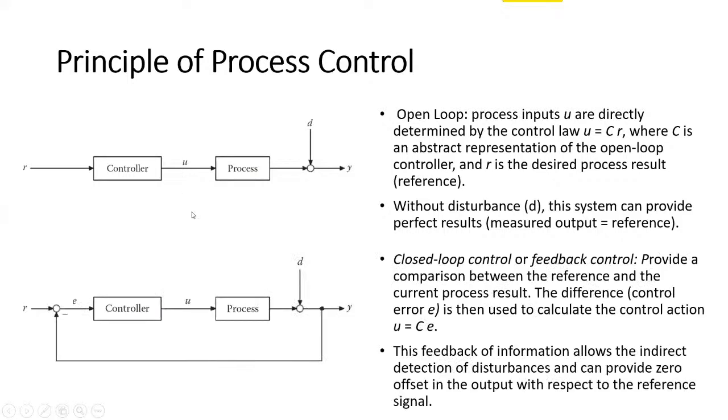So we now use a feedback control system. If there is any disturbance in the system, we can tell the controller that, hey, there is a disturbance here, so the controller will adjust the temperature or anything that we control, so the process variable here can be maintained at the desired value. What you see here is we only control the process parameter. We don't control the quality aspect of the product that we process.